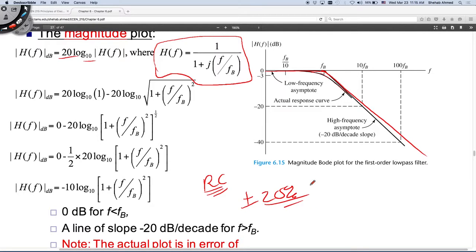But I will have to pay much more for that, because what they actually do is they don't manufacture a different resistor or capacitor. They manufacture everything and then they screen them. So if you want a specific resistance within a specific tolerance, they will screen these capacitors and resistors, and you have to pay much more for the screened version, because you designed your circuit to depend on such a tight tolerance.